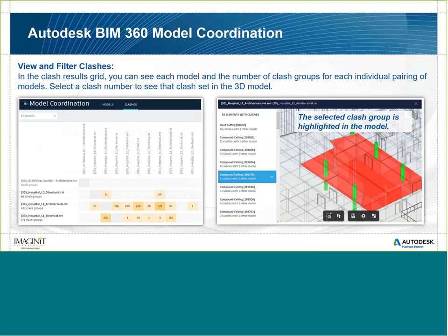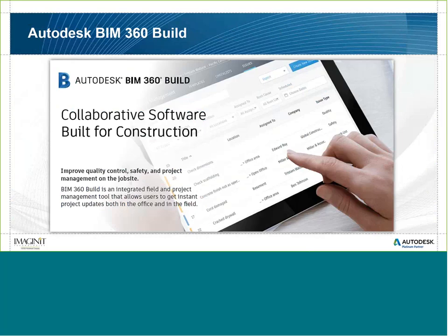And now that you've finished your model coordination and you're working with that in the construction process, of course, you're now looking at BIM 360 Build. Again, built on top of Docs, so Docs is still there as your master document management tool. And now you're using BIM 360 Build to manage quality control, safety on the job site, regular checklists of any type. You can create your own checklists, set them up and customize them the way you want to, meaning their content and the response types. And then people can fill those checklists out on the tablet device.